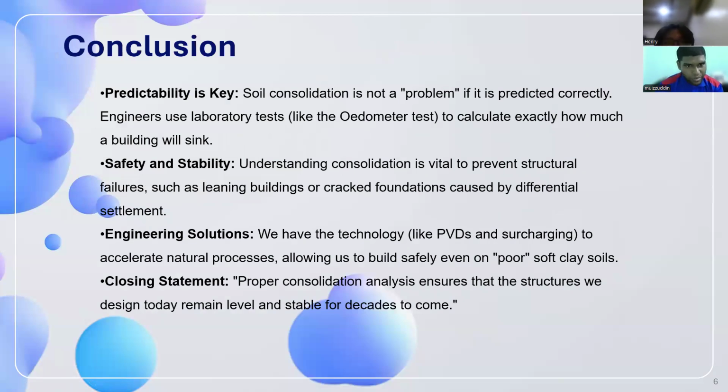In conclusion, predictability is key. Soil consolidation is not a problem if it is predicted correctly. Engineers use laboratory tests like the oedometer test to calculate exactly how much a building will sink.